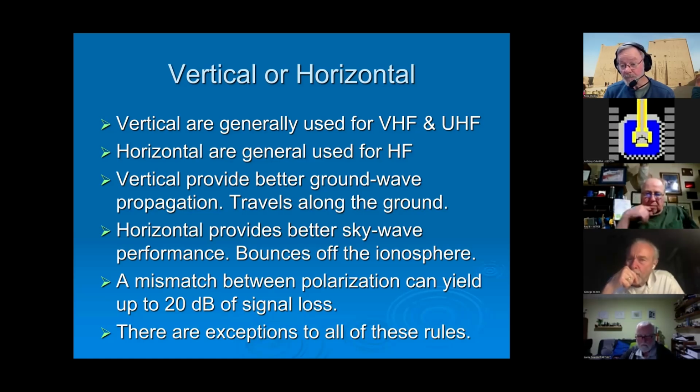Horizontal polarization means that most of these guys are going to be high frequency operators, using the ionosphere. The ionosphere is the magic that we get in HF operations where we get long distances, because that horizontal polarization does a nice job of coupling and dealing with the ground plane effect and getting up into the sky and traveling long distances.